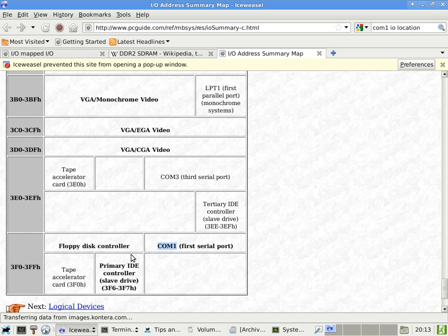When you read from that location, you're reading back the status of some sort of I/O device. And they may not be the same. What you write to that location may not be what you're reading back, because it is a portal, a window into an entirely different device. It is not memory. Are we doing okay in terms of the concept of input-output space? Okay.